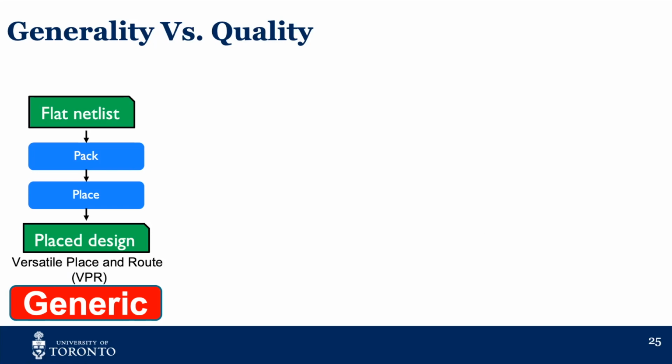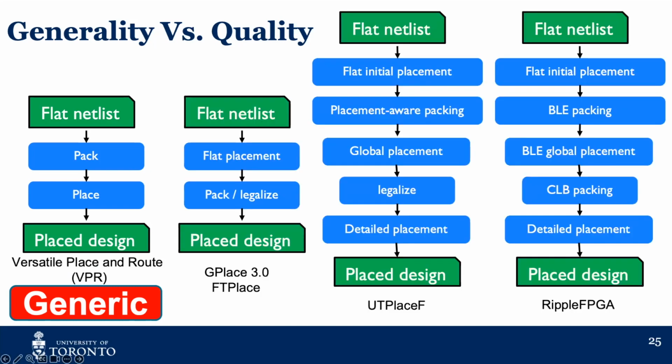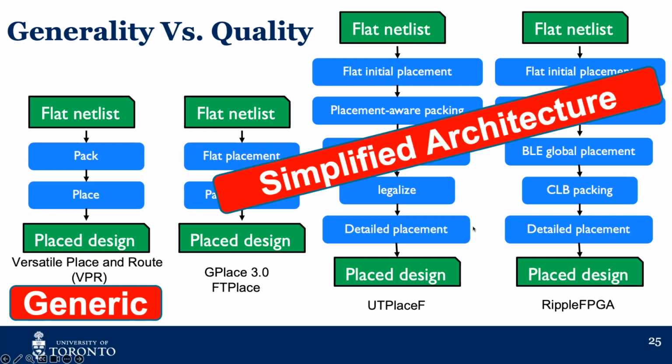only based on the logical connections. A whole bunch of different ideas to break the boundary between packing and placement stages were proposed in different works, and they reported promising quality of results. However, most of them only deal with logic blocks and neglect important blocks like carry chains, and they use simplified architectures with pre-packed RAM and DSP blocks. Although there are a lot of interesting ideas and algorithms here, they aren't broadly applicable because of all the shortcuts